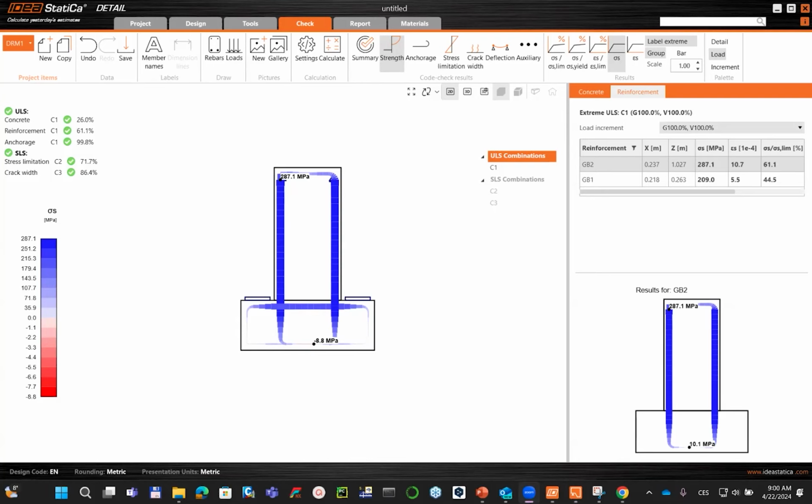Shear caused by the girder self-weight and other loads acting on the top of the beam. Can you account for this in a single model in IDEA StatiCa, or do you have to perform two models? It's very simple to say: you have to perform two models. The first one in the reinforced cross-section, the second one as well. I think you answered your question. So you need to use two models.